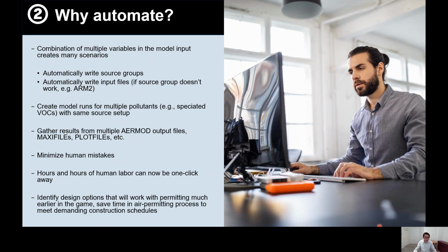Or in some cases, source groups won't work, and then we need to write many input files. For example, when ARM2 is turned on in NO2 modeling, you won't be able to use source groups. That's where you have to do multiple input files, and we'll see how automation will help.